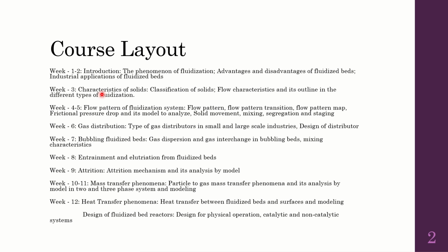Next come the Geldart B particles. These are widely used in fluidization because they have a controlled bubbling phase. Geldart B is larger than Geldart A particles, and they are used in various applications. Next come the Geldart D particles. They are the largest particles. They cause spouting and are easily carried away, like they would be moving as a group. So they are used in spouted beds.